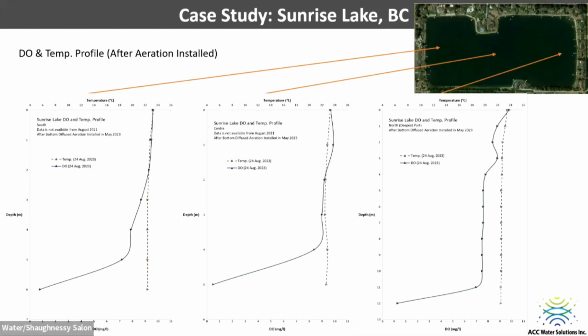Their plan originally is to run this thing just in the summertime. We've told them run it 24/7, 365 until you can get to the point where you have degraded the nutrients enough in the deepest parts of the water body year round, so that you eventually get to the point where in the summertime you can meet the oxygen demand. At that point in time, you can start running the system intermittently. You can set it so that in the winter months you turn it off altogether. In the spring and fall you only run it a few hours a day, and you only run it full time through the summer, so you get better energy efficiency.